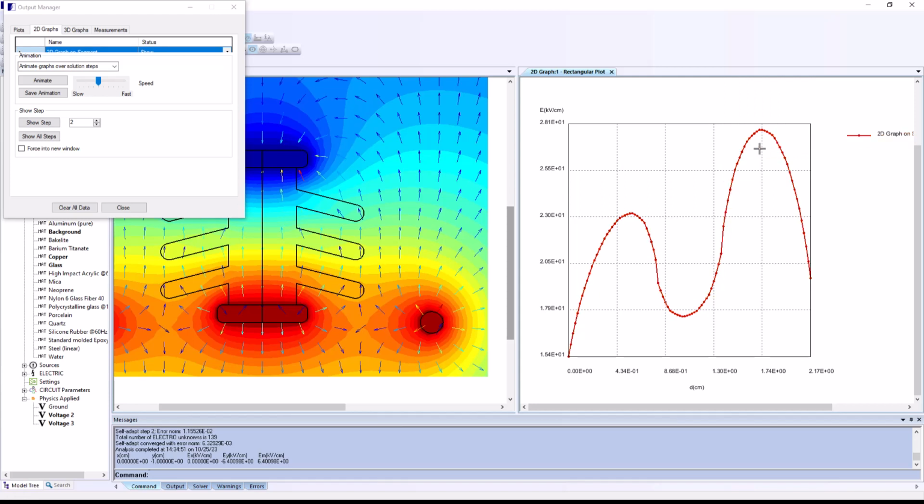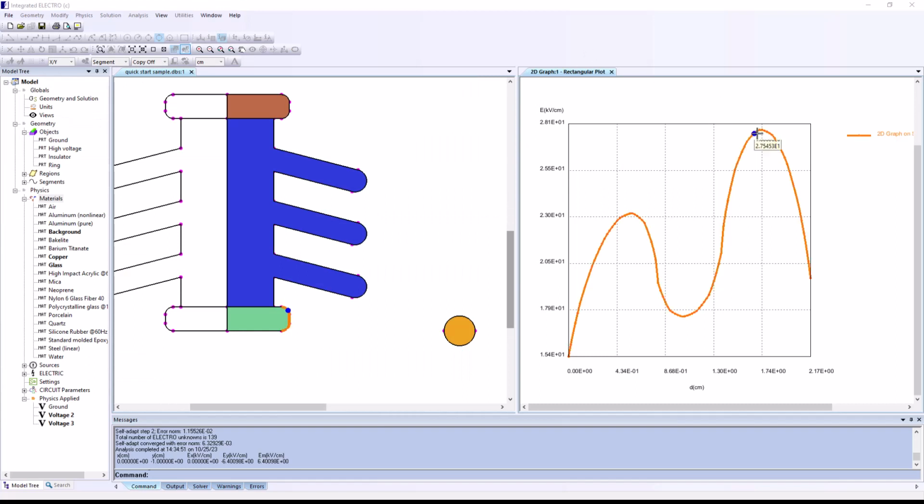Right-click on the graph curve and select Trace. The curve highlights corresponding geometry in orange in the model window, and a blue dot indicates the current trace point. You can now easily identify where plot features occur in the geometry by moving the mouse across the graph.